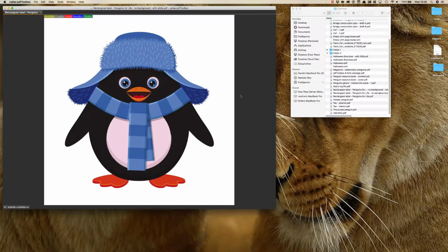When I open documents in pdfToolbox, it is shown just as it would be shown in Adobe Acrobat itself. Actually, the display that you get here is exactly the same as the one you would get in Adobe Acrobat, because pdfToolbox also uses a built-in Adobe PDF library. So you're sure that what you see here is going to also be what gets printed at the end. And that's important. Things like overprint preview are always switched on in pdfToolbox, so you have no way of forgetting this or misconfiguring this.